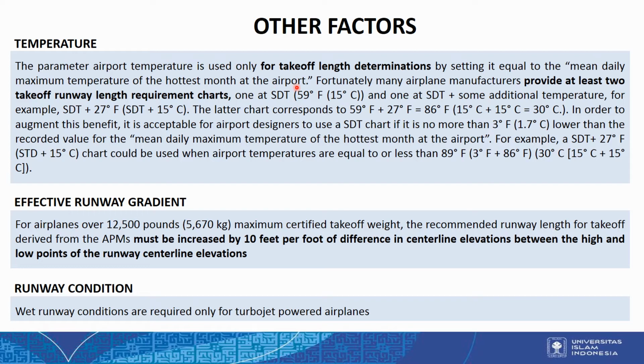Usually airplane manufacturers will provide at least two takeoff runway length requirement charts. The first is at the SDT, or standard day. The standard day is 59 degrees Fahrenheit or 15 degrees Celsius, and the second chart is for standard day temperature plus some additional temperature.